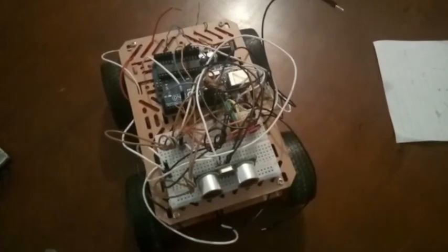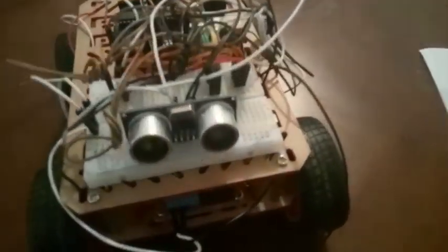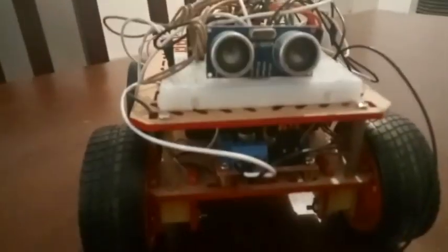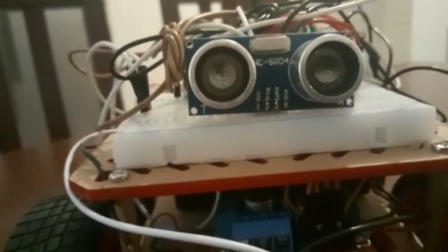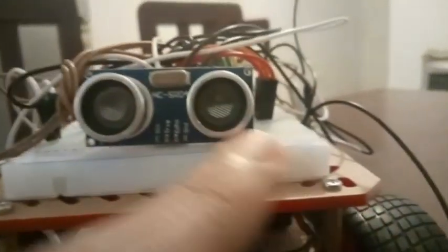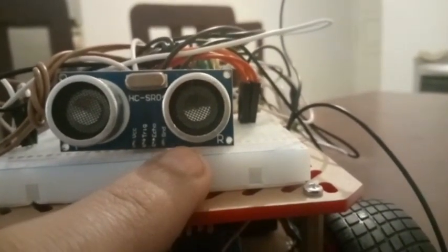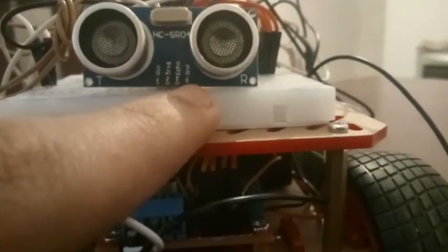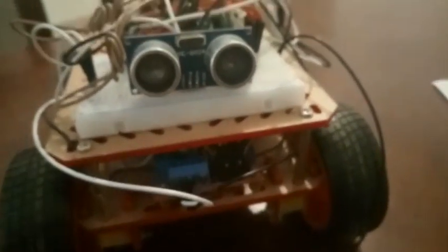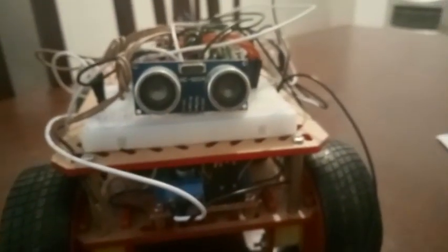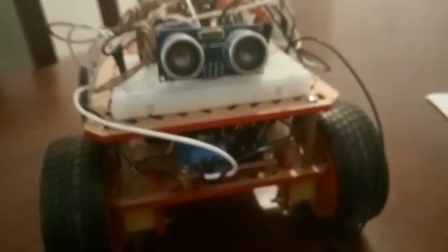And now I'm going to explain to you how we connected the ultrasonic to our car. We have put it in front of the car, so whenever it detects an object in less than 30 centimeters, it stops immediately. Here we have the 4 pins, the ground and the VCC, and the trigger and the echo pins that are connected to the Arduino. So whenever I have an object like my hand over here, it makes the car stop immediately if it's less than 30 centimeters in distance.